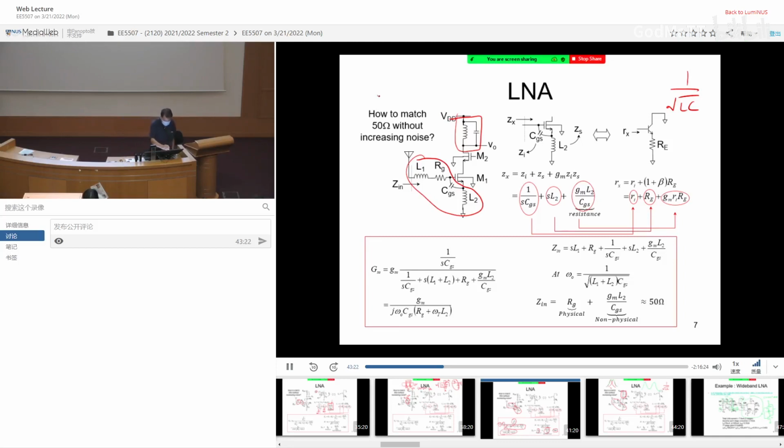But what if I have this kind of resonance? That is for the input. This one, I get another one, slightly shifted. You combine them, you're going to get something like this. Am I right? So this is a very popular technique people call staggering. Stagger tuning, right? Stagger resonance or something like that. So basically, the resonance shifts a little bit, making it wideband. Now, of course, you cannot shift too much. If you shift too much, then it becomes something like that, dual peak.